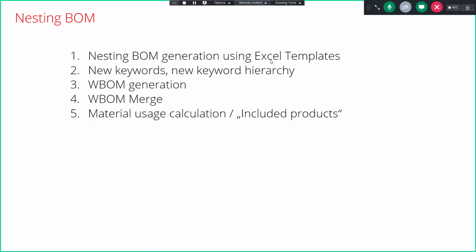Okay, now let's take a look at the nesting BOM. This is another strong nesting feature, because you need to know how much workpieces you will utilize. Yeah? And the area on the assembly BOM is not the same as the area on the nesting. Yeah? So maybe you have part of 1 square meter which goes diagonally through the workpiece, and you need to waste all that workpiece. Yes, or maybe you have like a nice rectangular item that will fit perfectly. So that's why the nesting BOM and the BOM of the assembly is not the same.